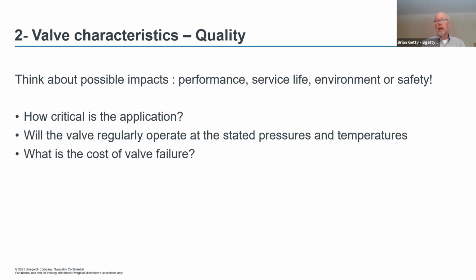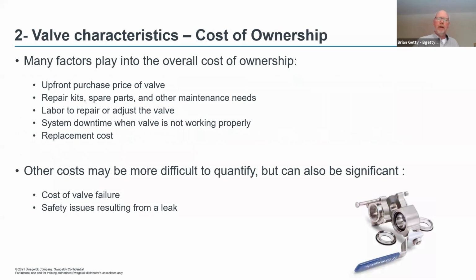Is this one valve going to stop that production from happening? So you want to look at your quality and where is it going? What is the valve doing? Very, very important. Also, if it's a valve that's going to be operating at its max pressure, max temperatures frequently or all the time, at that point you want to go with the best quality you can find, because the cost of doing repairs will significantly outweigh the purchase price of the valve. Your cost of ownership.